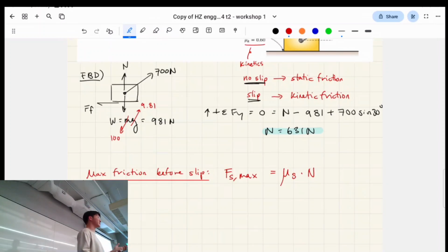How this might make sense is if you think about, you wrote something on a paper with a pencil, right? And you lightly rub it out. Say it doesn't rub out, right? So what are you going to do? You're going to press down on it harder and rub out, and that gives it more normal force, which gives more friction force, and then the pencil will come off, right? So that's why friction force is a function of your normal force, actually.